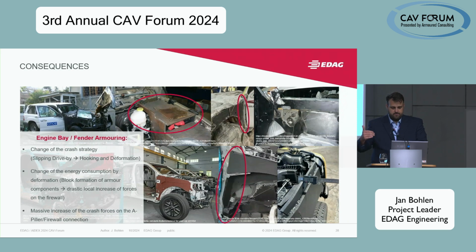You change the way the energy is consumed in the vehicle, and due to the rigidity of the parts, you have some block formation of these armoring components quite locally on the firewall of your vehicle, and that will lead to excessive forces on some local points, especially on the connection of the A-pillar and the firewall, and right behind that is the driver of the vehicle.